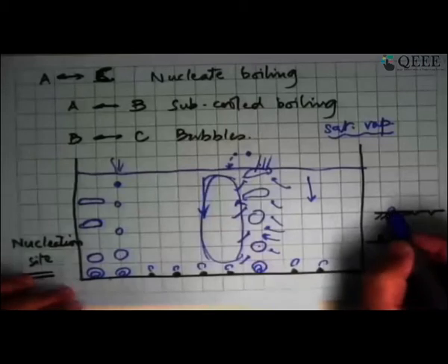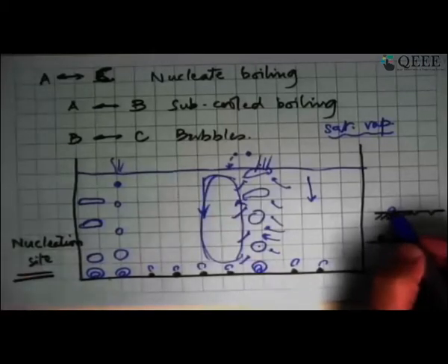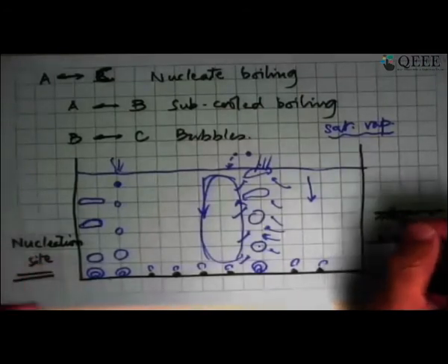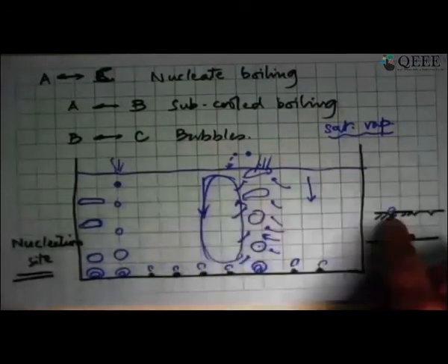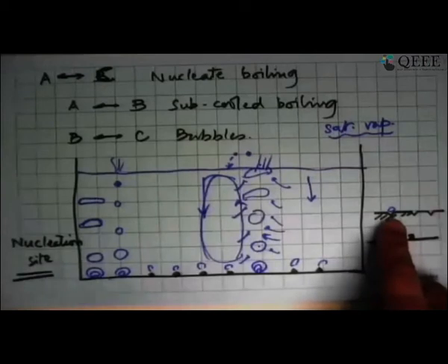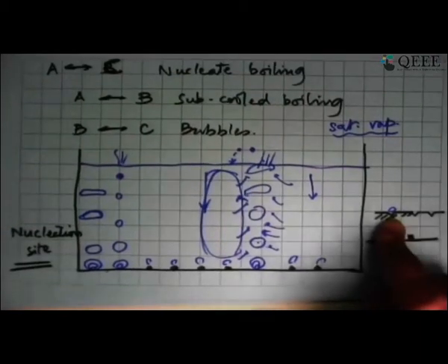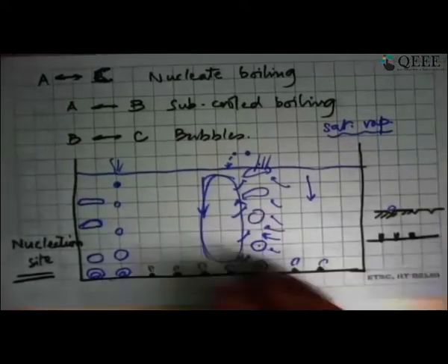And the other thing is, because locally the heat transfer is high, the temperatures are higher, this nucleation site will continue to wear out slowly. It will cause failure of the material at that point. And that's what happens in power plant tubes, where at one point there's a lot of nucleation taking place which was not expected or controlled, and that is where the tube thickness will slowly keep decreasing. Internally it is pressurized, so at some point the tube will burst. And that's a very common occurrence in boilers, in power plants.